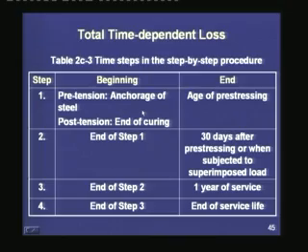That means for a pre-tensioned member, once we have anchored the steel, we take some time to cast the concrete, cure the concrete, cut the steel and transfer the prestress. But by that time there is some relaxation loss of the steel because it has been held against the end abutments.